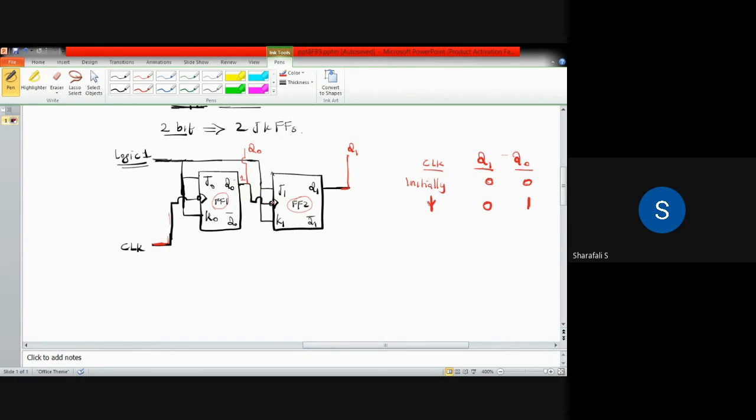If you take note of that, it will be 0, so this Q1 will not be toggled, so that will remain in the same state. And for the second clock edge, we have Q0 now 1, and that one is noted here and given to this flip-flop, so this Q1 will be 0, that is, not toggled.